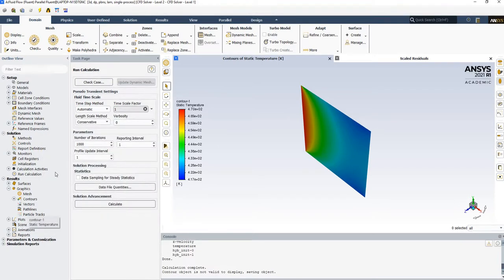Okay, so this is how you can set up a purely surface radiation model. Again, the important point is you should only use the surface radiation model when the medium, like in our case air, does not scatter the radiative heat transfer by a lot. If there is a significant difference, like it can change the incident radiation, which would change the result of the actual scenario you want, make sure it is not like that.